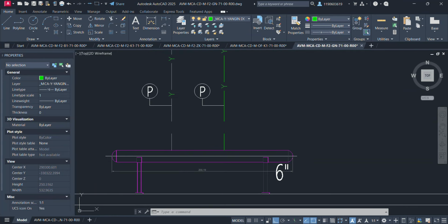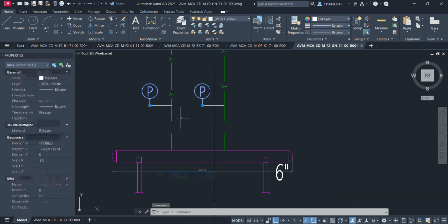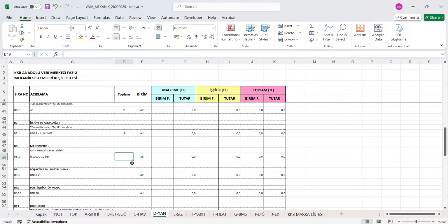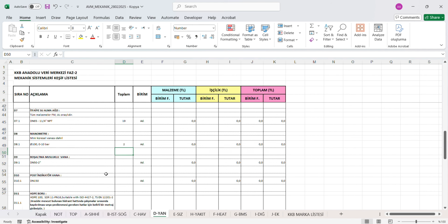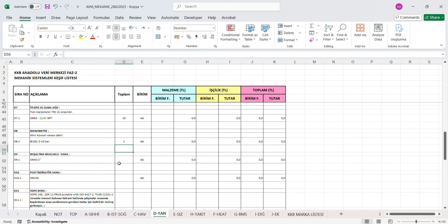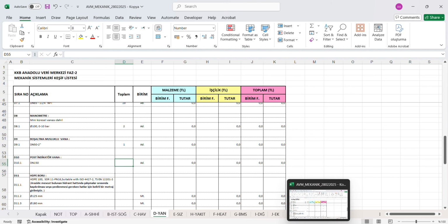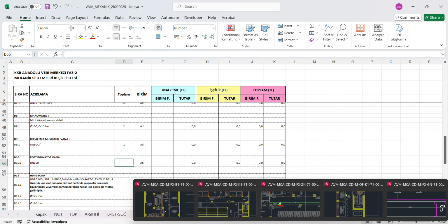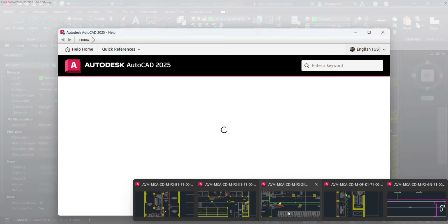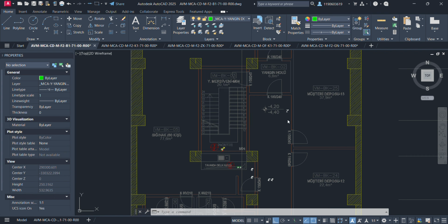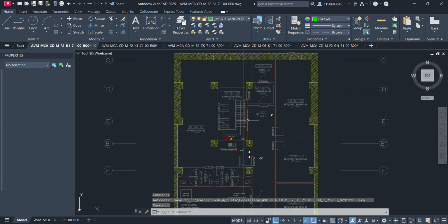Technical specifications for fire tanks. Sturdy structure. Tanks should be made from corrosion-resistant materials, such as stainless steel or galvanized steel, to ensure durability and a long service life. Proper connections. The tank should be properly connected to the pipe system and hoses leading to the sprinklers or water pumps. Regular inspection. Tanks should undergo regular checks to ensure there are no leaks or blockages that could impact the tank's ability to store or deliver water effectively.